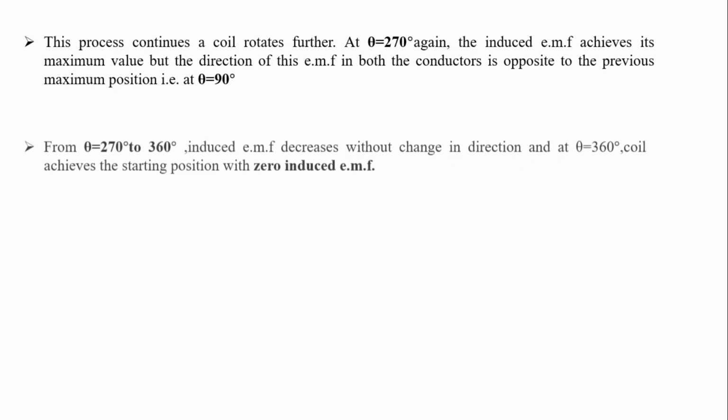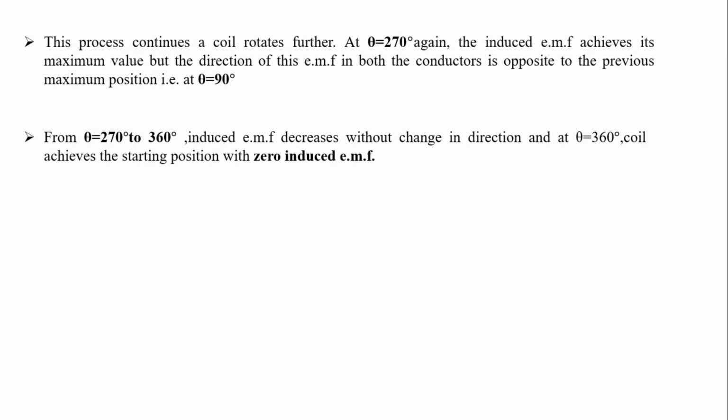From theta is equal to 270 to 360 degree, induced EMF decreases without change in direction, and at theta is equal to 360 degree, the coil achieves the starting position with 0 induced EMF.